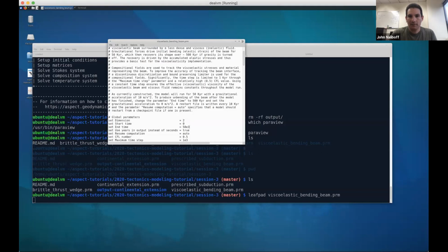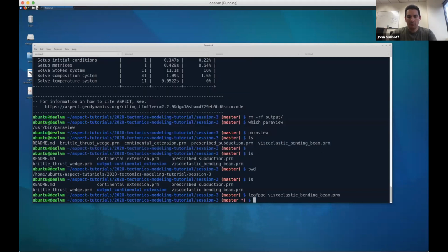So once you've done that, please close it, and then we can start running the model. And the command for this, at least if you're running in release mode, would be tilde aspect /aspect -release, or whatever you named the release executable. If you're just running in debug mode, aspect-release would just be changed to aspect. And then, I forgot to add, at the beginning of this you would need to have mpirun -np 2, which is what I will use.